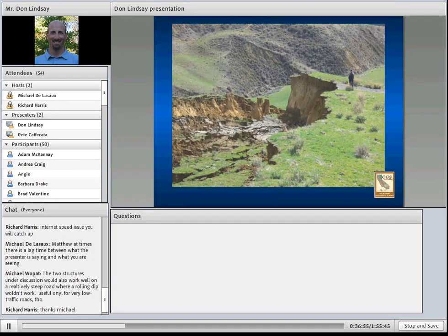Here's another photo of an active and potentially active slide in real life. In the forefront is the lateral edge of an active slide, and off in the distance on the other side of the drainage, you see irregular hummocky to benchy slopes with areas of isolated debris slides extending down the channel below. You'd really need to do your homework in order to find suitable locations to discharge concentrated flow in this type of terrain.